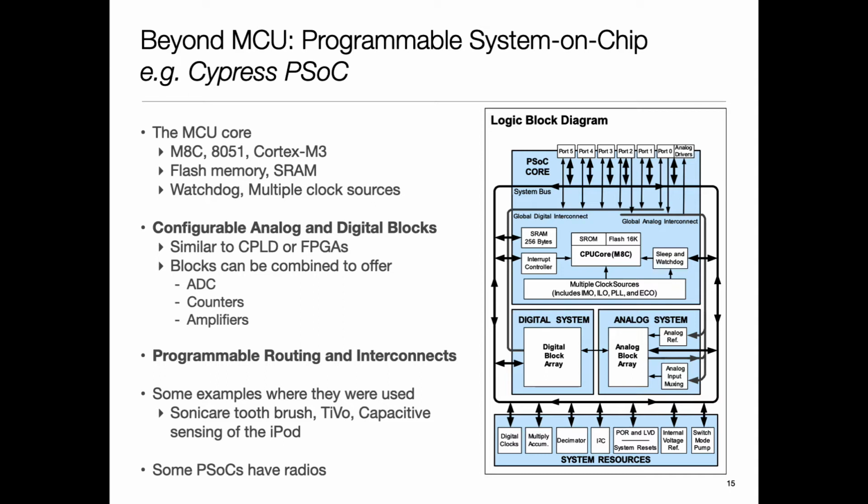Nowadays, a challenge when you integrate all these things is that it's kind of a jack of all trades. So it's very hard. If you think about how memory is made, DRAMs use special processes. Semiconductor processes are different. If you're making an analog component, again, it has different requirements. But if you're trying to put everything on the same silicon, then the challenge you face is that you have to compromise. Either the digital part would be non-cutting edge, or analog design becomes more challenging.